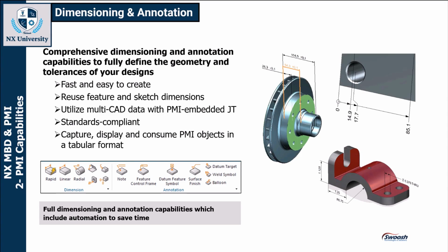Also, we can utilize multi-CAD data with PMI embedded JT. This is also standards compliant, so based on the two standards we spoke of a moment ago, we can use those standards to help us have the software run some checks and ensure that these are being applied to the features correctly. We can also capture, display, and consume PMI objects in a tabular format if we need to do that.